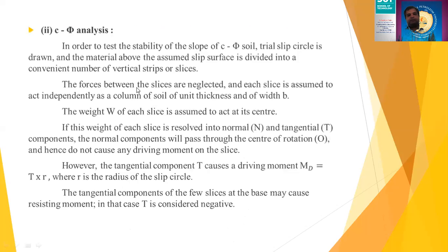The forces between the slices are neglected, and each slice is assumed to act independently as a column of soil of unit thickness and width B. Please see carefully. I will go back to the figure.